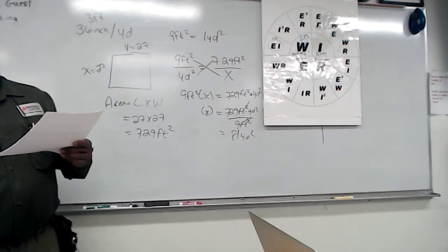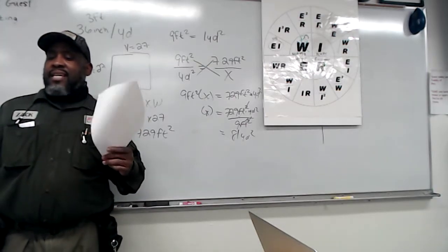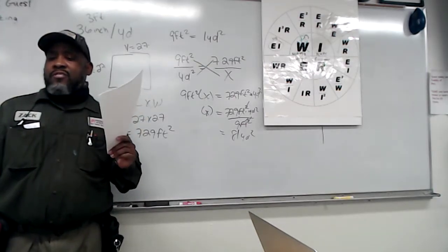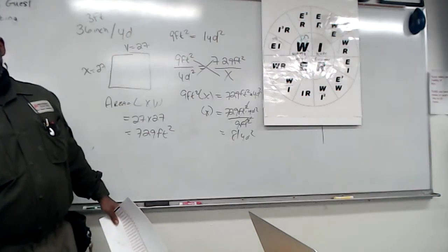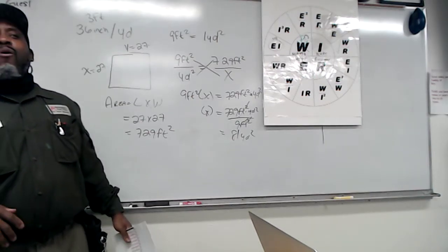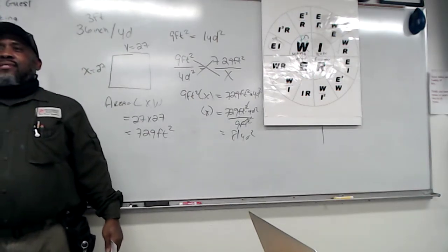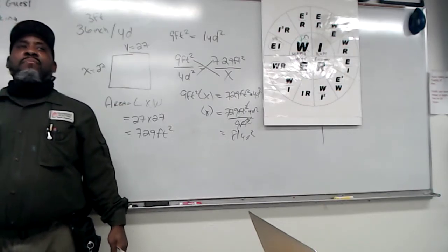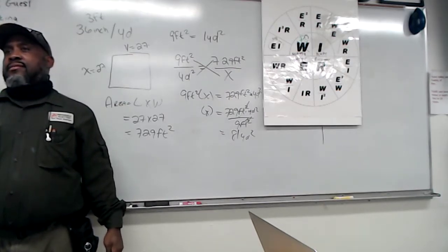What about this one? That's one I got wrong. If this kitchen layout is in an office building, the NEC requires how many receptacles to be installed in wall space A? What's the answer? 0. Why? Because it's not a wall space here. Anybody else? That's what I chose.